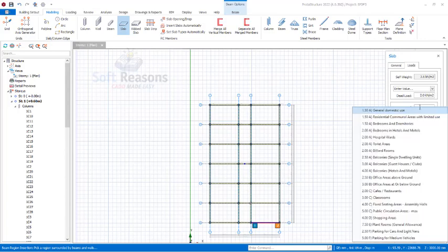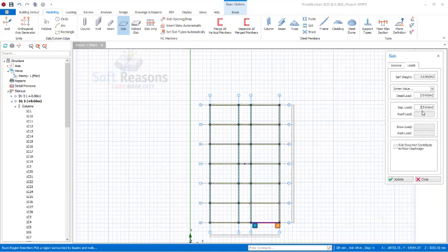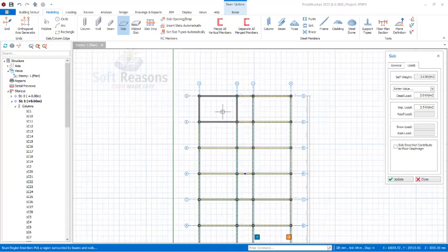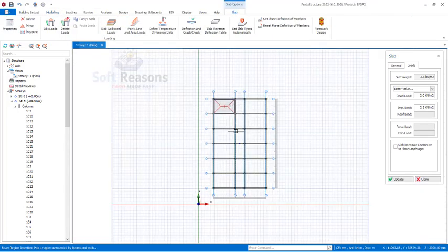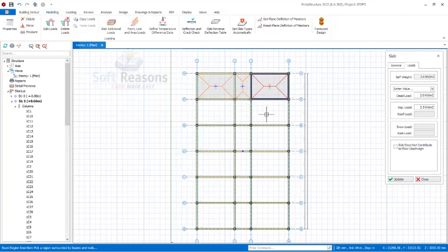So for the imposed load, we will check an imposed load. We can use hospital ward, or we can use the workshop, shopping area, parking area. So you just have to use any of these. Let's use the one that is carrying 2.5 kilonewton per square meter for the slab. So we just click inside of this to have our slabs placed within the beam regions, just like this. All right, so we have this just like this.